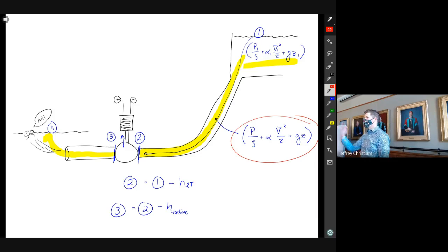So that would be something that could come out of your report. If minor loss coefficients change the overall system efficiency significantly, you want to make sure you highlight that in the report. You can say, this is how we optimized it, but when we design our final system, this is a part we really have to key in on because this is hugely important to the performance of the system. We're going to have to look at how we're designing inlets and exits and bends, and make sure we use really low loss valves. It matters a ton.